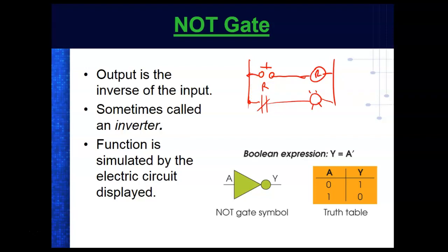If I'm not pressing that button, so this rung is false, this rung is true. So it's inverted, right? That makes sense? Yeah. So when this rung is false, this rung is true. When I press that button, this relay coil comes in, opens that contact. So when this rung is true, when I close this rung, down here goes what? So when you look at the contacts, you got to understand it's not the contacts, it's how we wire what's controlling those contacts.